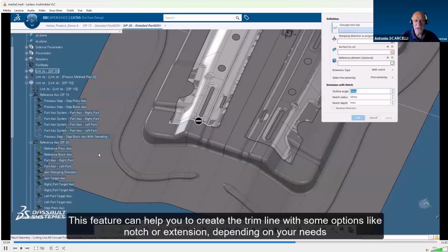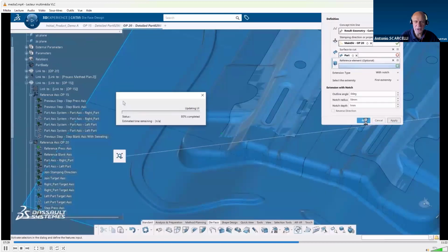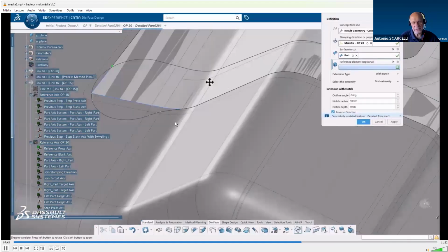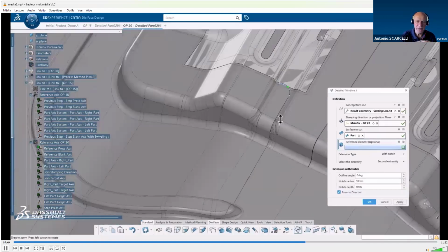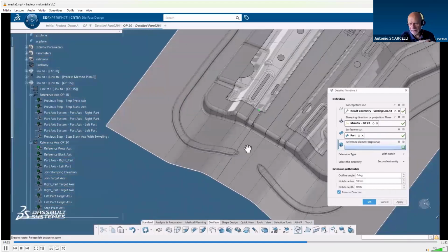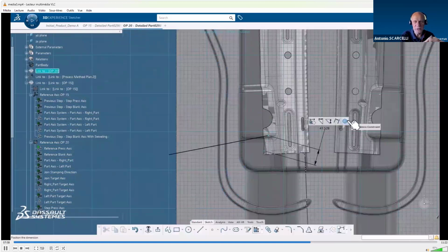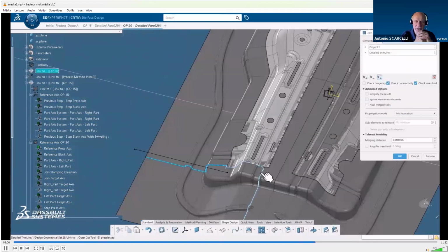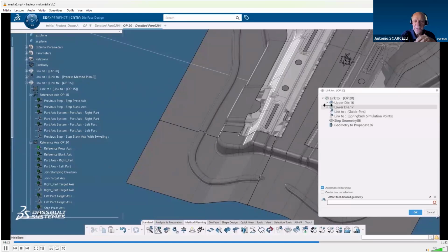To do that, we are also using a MODSIM application, a dedicated one, in order to project the curve on the die face. And with this capability, in general, on some areas we are managing the knock, and we are also managing the overlap between the different tools. Because at the end, if we don't use these methodologies on your part, you will have some extra geometry or some extra sheet metal that is remaining that we don't need.